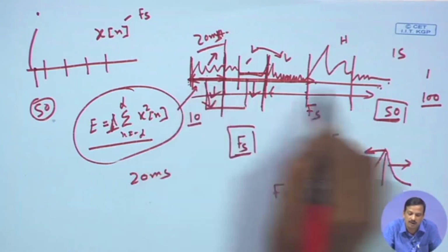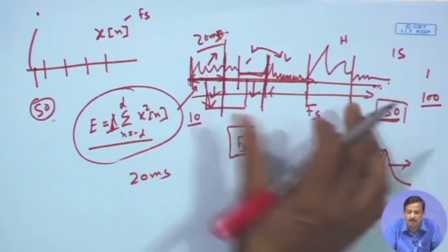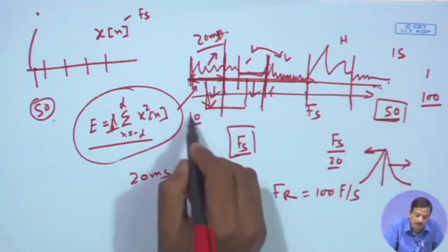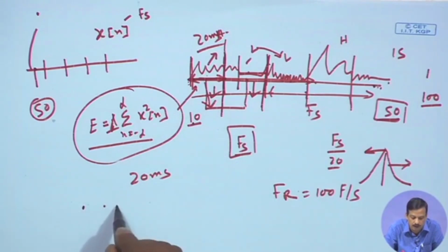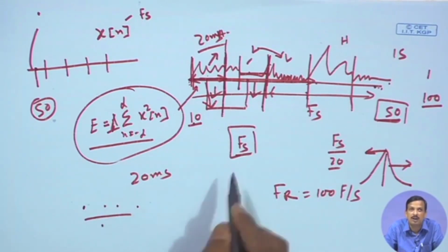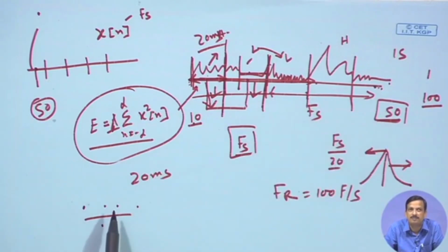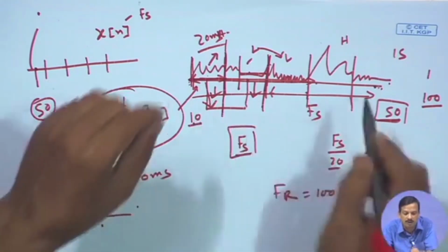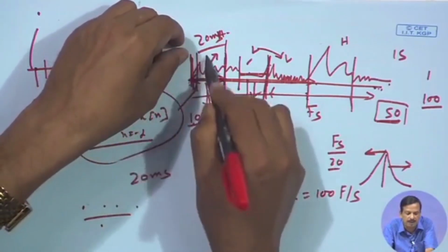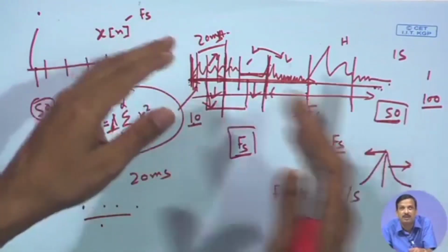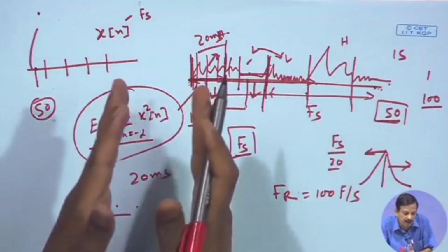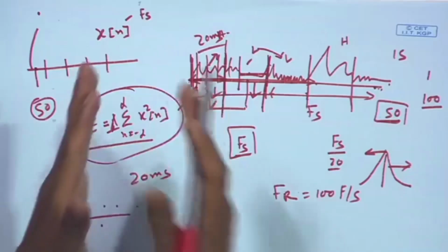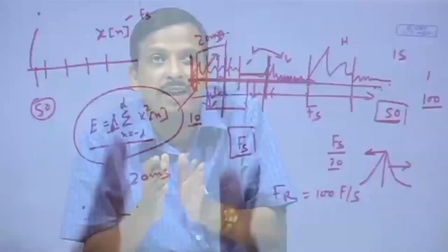Here, for the sampling frequency, I get Fs number of samples per second. Now, if I say for every 10 millisecond I take a point, then I get 100 points in a 1 second signal. So, I can say it is a downsampled signal. If I want to process the signal, taking every sample is very difficult, because if Fs is 8 kilohertz, that is 8K samples. So, instead of 8K samples, I divide that whole 1 second signal into 100 frames, and for every 10 millisecond I get a parameter.